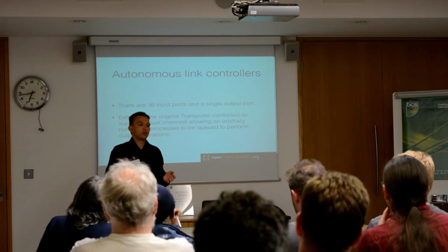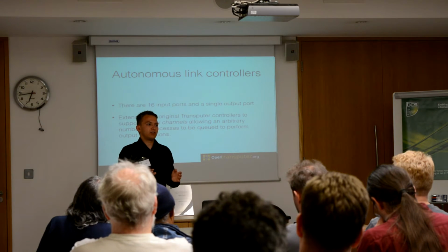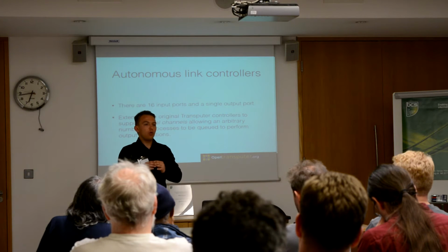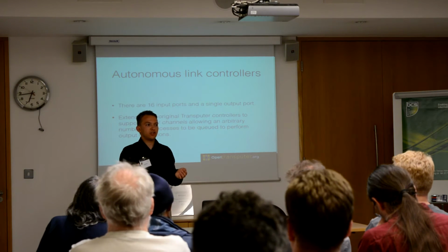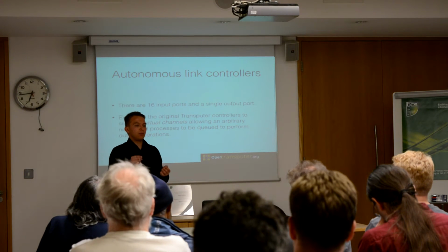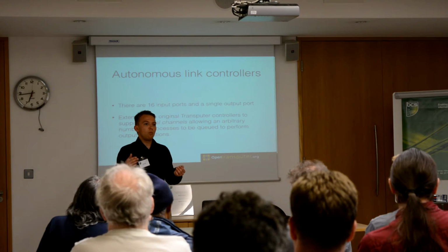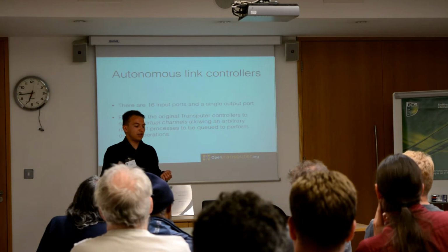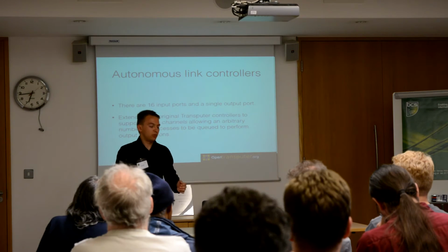We also introduced the notion of virtual channels. In the original Transputer, only 4 processes could be performing external communication at the same time. In the OpenTransputer, you can have an arbitrary number of processes waiting for external communication. We also increased the number of input ports from 4 to 16, and we have a single output port.